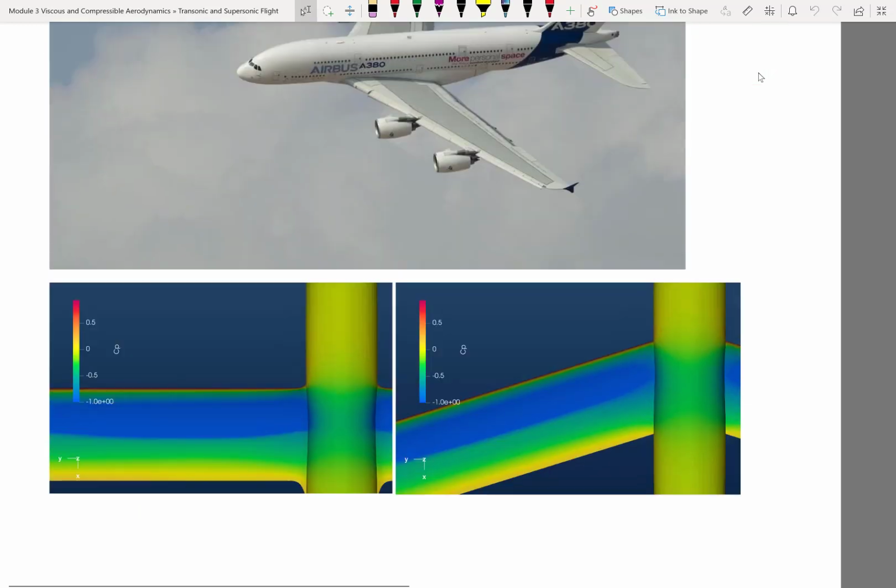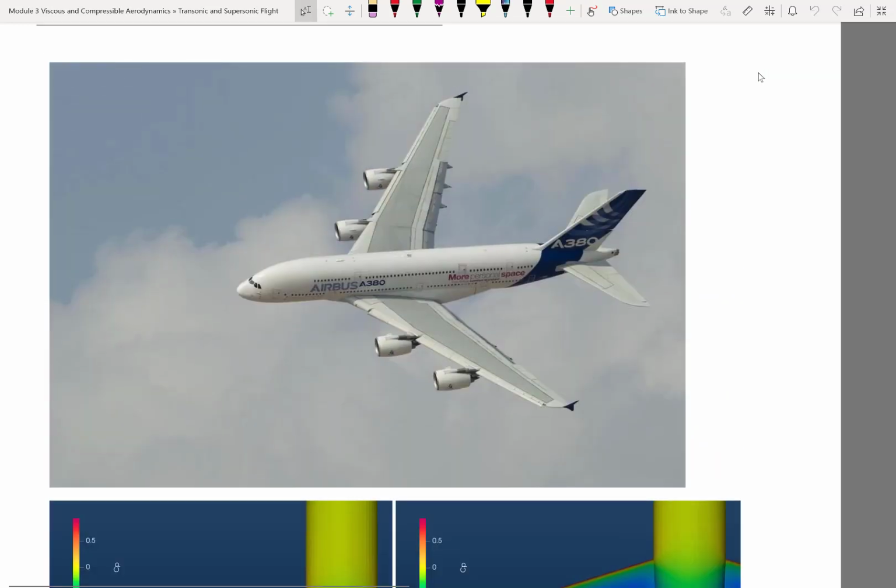So you see, transonic airliners have just a slightly swept wing. Well, because they're not flying at Mach 3, right? So this jetliner might be flying at, let's say, Mach 0.8, which means the maximum speed on top of the wing might be Mach 1.2, right?